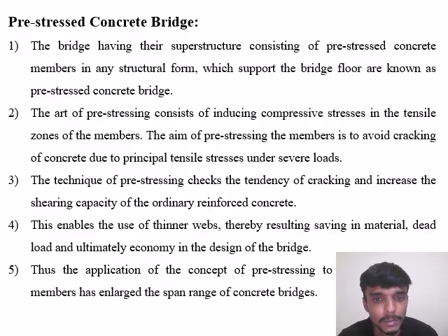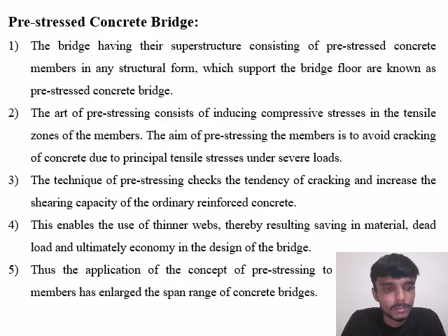The art of pre-stressing consists of introducing compressive stresses in the tensile zones of the members. As I said before, pre-stressing means the cables are stressed before the concrete pouring and then released. So the tensile-stressed cables will try to contract again due to their elasticity.